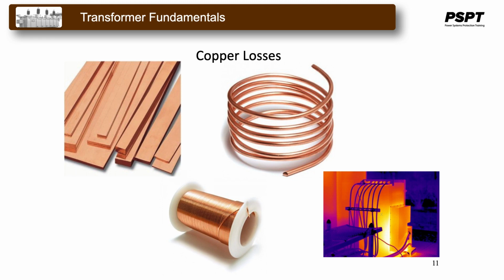Not only that, when a load is connected to the transformer secondary windings, large electrical currents flow in both the primary and the secondary windings. Electrical energy and power, or I²R losses, occurs in the form of heat. Generally, copper losses vary with the load current, being almost zero at no load and at a maximum at full load when current flows at a maximum.